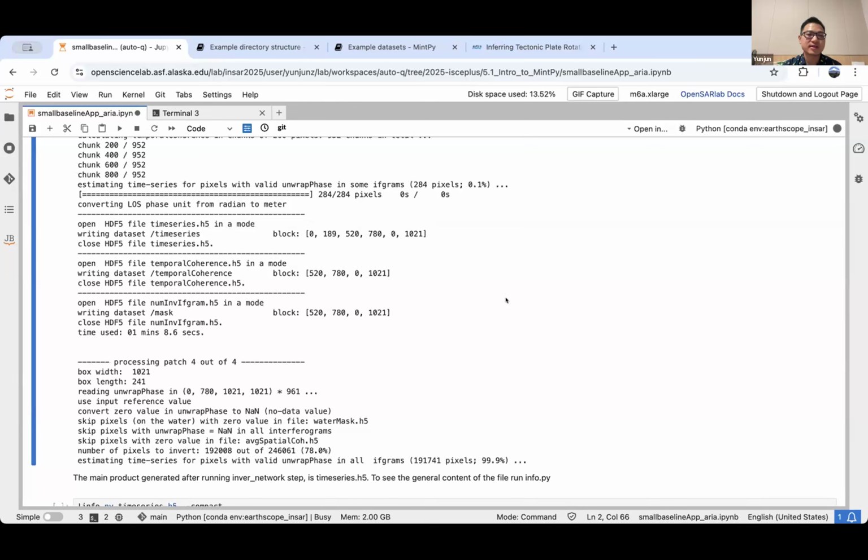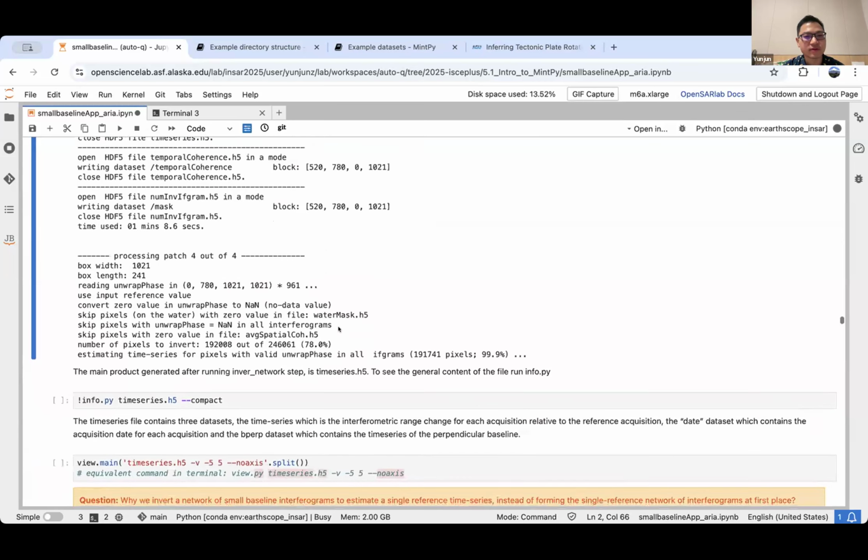So in this step, you can see it spends some time, even though it's not so slow. But if you run a bigger data set, you will find it is actually the most time consuming step in the MintPy analysis. So what you can do afterwards is, first, don't turn on the weighting in your first run, because weighting makes everything pixel-wise and makes things extra slow.